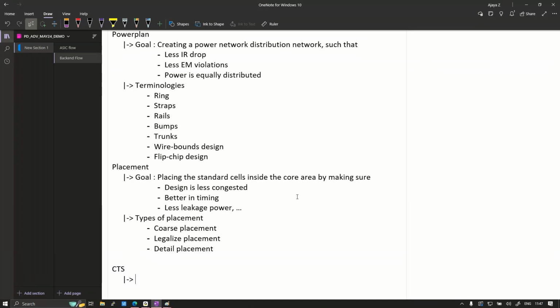But now when we talk about this from a design perspective, as every sequential circuit starts to run at the same time, the power requirement of that particular device will be high, right? As every circuit starts running at the same time, leakage will also be high. Next, we will have multiple violations. So will the data be received properly? Will it be transferred properly? No. Multiple failures, right? So that's why a small variation has to be kept. This is actually an interview question.